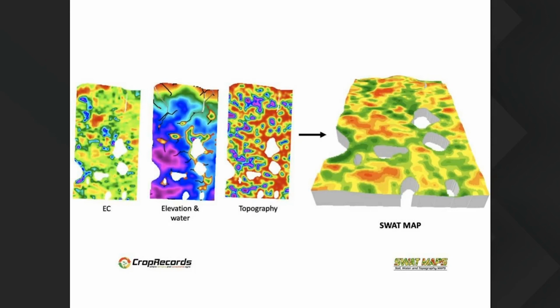So here's the electrical conductivity layer. On the left, the red areas are actually really low, definitely not saline. All the salts are leaching through, and all the solutes, so mobile nutrients, sulfate, chloride, all those sort of things, really leach right through. On the other hand, the high EC areas in this particular field are actually saline. So they grow very little crop, actually on the verge of being solonetzic as well, with a little bit higher sodium. So very poor soils.